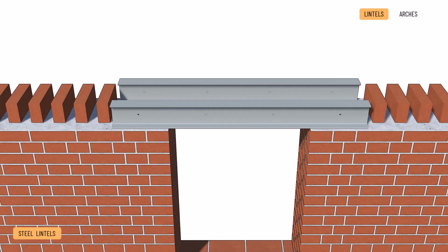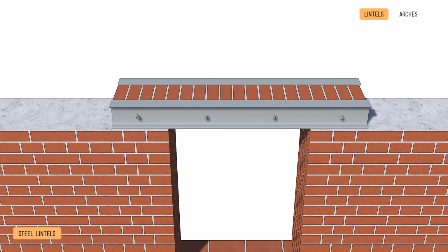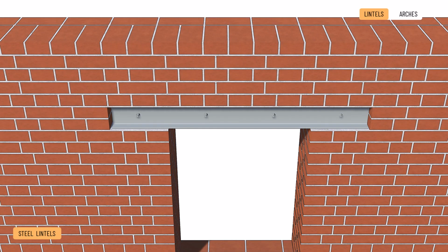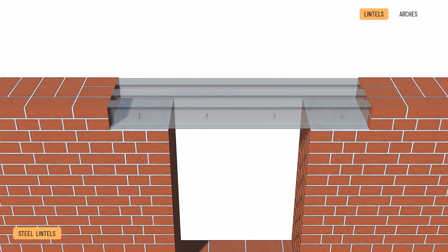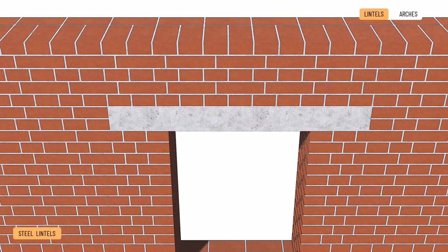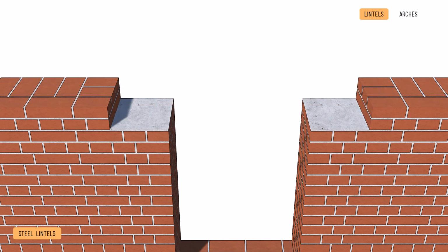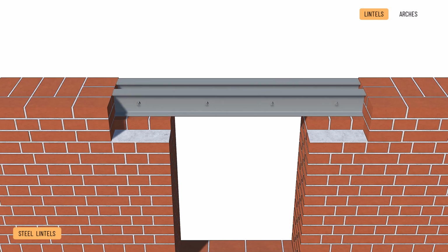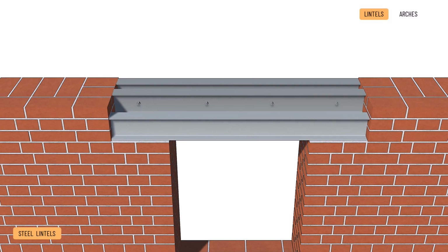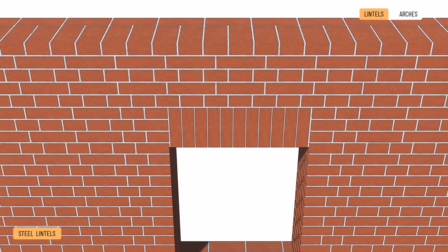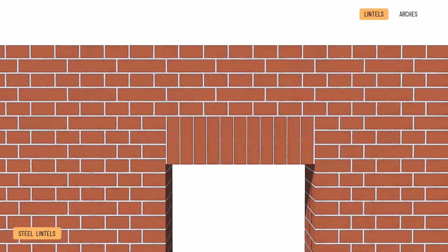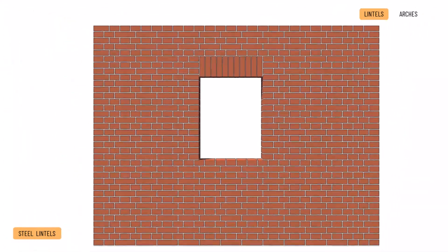Bricks are often placed between the steel beams with a protective coating over the beams. Alternatively, you can also plaster the beam with a mesh around it to protect the steel from corrosion. Also, the space around the beams can be filled with concrete by either shuttering the entire cross-section or forming a lintel casing. Aesthetically, it was particularly favourable to use a brick course of the same material as the brickwork, suspended on a steel wire fixed to the concrete back section.